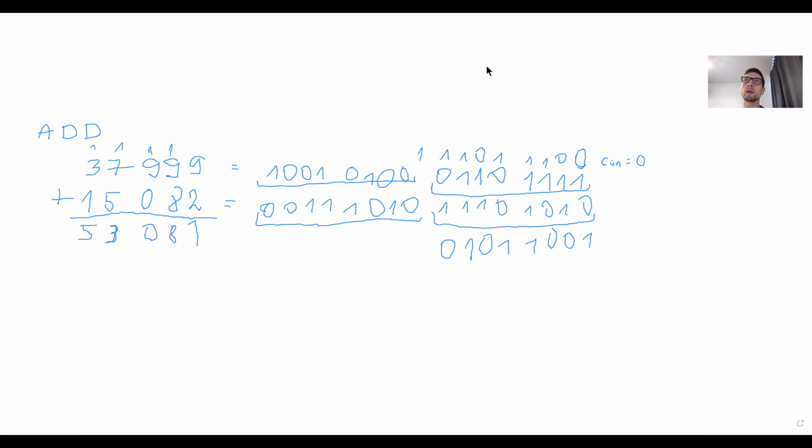But what processors do have is something called the status register, short for SREG. I'll write it with text. Status register. It is a special small memory cell in which some bits between operations are stored. And one of such bits is the carry bit or carry flag. The contents of these status registers are often also called flags. So one of the flags inside the status register is the C flag. Maybe I'll write it with text.